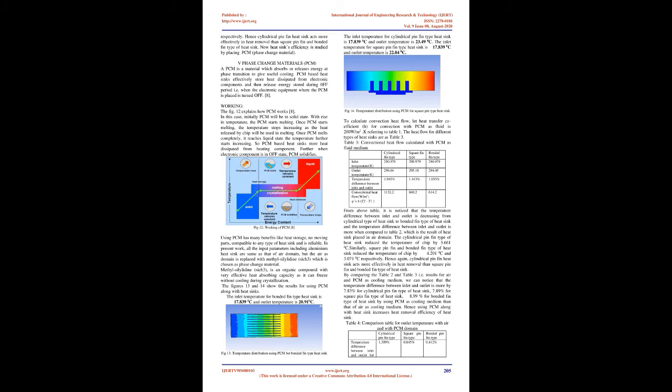So PCM-based heatsinks store heat dissipated from the heating component. Further, when the electronic component is in off state, PCM solidifies. Fig 12, working of PCM. Using PCM has many benefits like heat storage, no moving parts, compatibility with any type of heatsink, and is